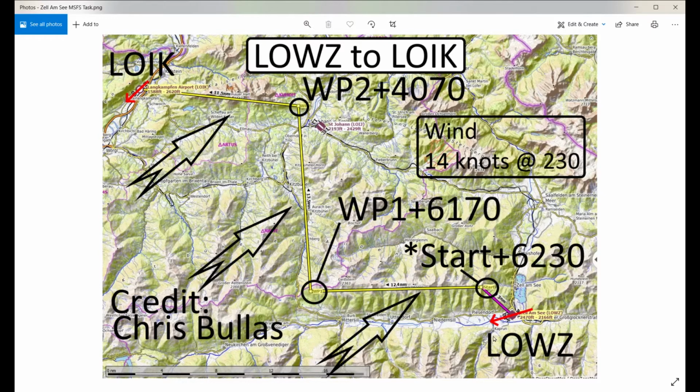And you can see in both cases, we'll make sure this flight starts with you on the right end of this runway, i.e. you want to be facing roughly southwest, because you're going to take off into wind. And the destination airport has the runway aligned diagonally in this way, so understandably we're going to want to come in, turn left and land so that we're landing into wind. But you've got to keep that in mind. There is a wind instrument in the glider that will tell you.